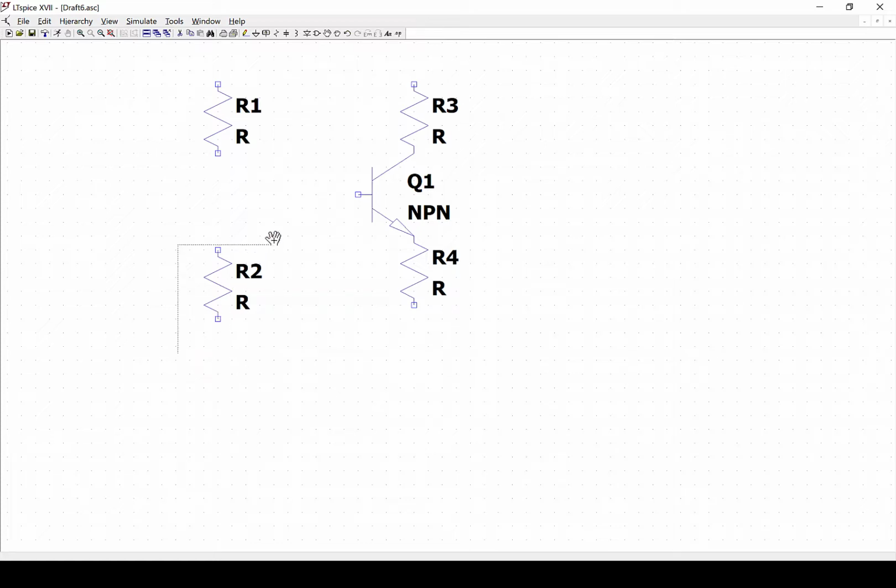So say that in this way, you might have seen that I have already connected electrically the resistor R4 with the transistor, as you can see over here. And I have done it because I have overlapped the small pin, which is this little square of the resistor, with a little square which is representing the contact, in this case of the base, of the transistor. And if you put one on top of the other, you create already an electrical connection. This is one way of creating electrical connections.